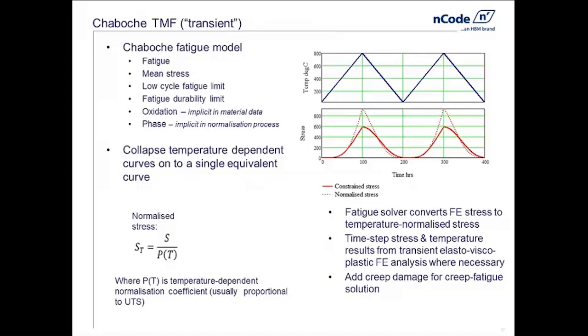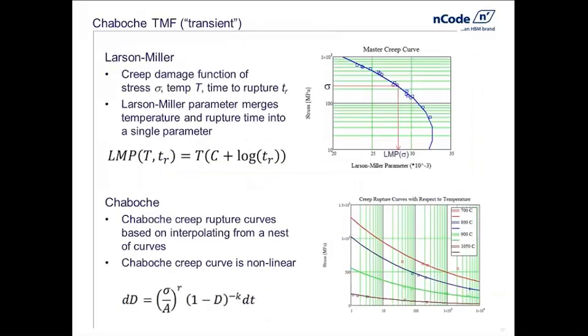Finally, when we have these long duration thermal stresses, we typically will see creep. Fatigue is caused by changes in stress. However, creep is caused by just a constant stress. And if we have a stress state at a temperature over time, we run the risk of seeing creep. Besides having this additional strain, eventually creep can cause rupture, failure.